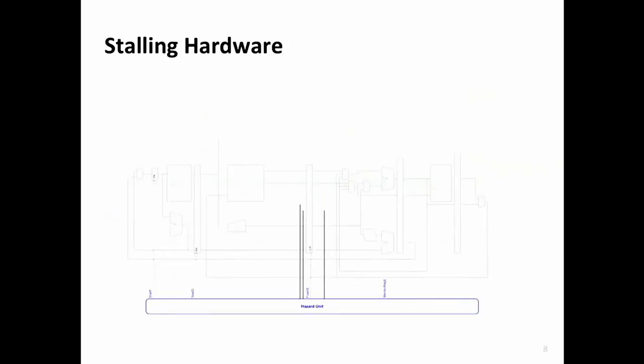Basically, if you look at this, you can examine the slides, or also read from Harris and Harris. These stall signals are asserted such that you don't overwrite the latches, and you flush the execute stage. You insert a bubble over here instead of moving the AND over here. Okay, that's hopefully simple. It'll get much more complicated next week.